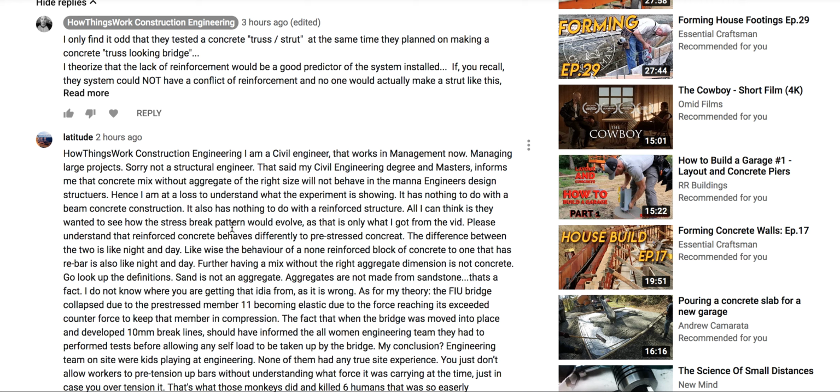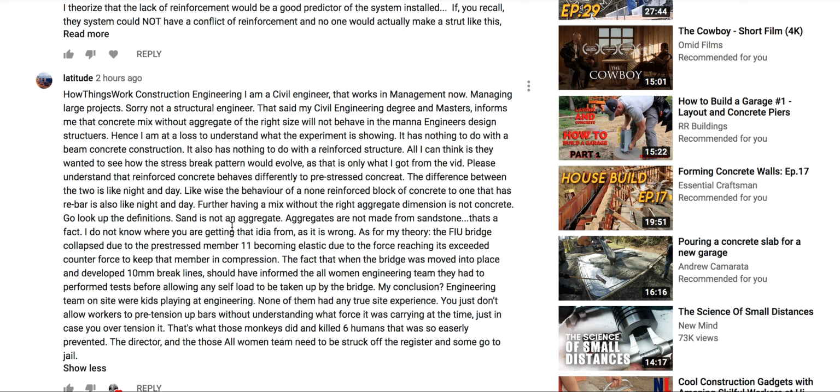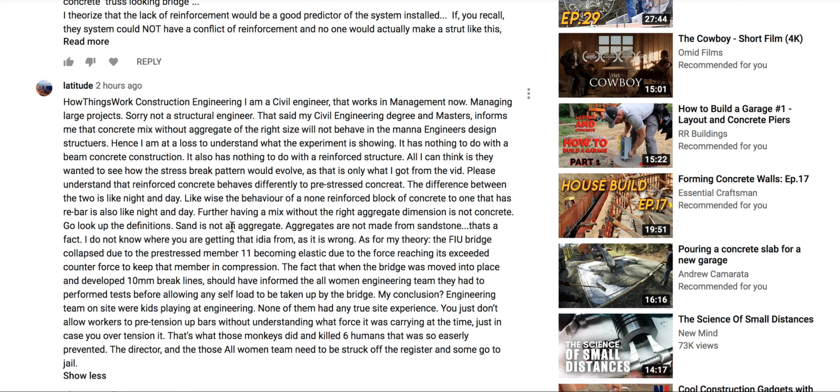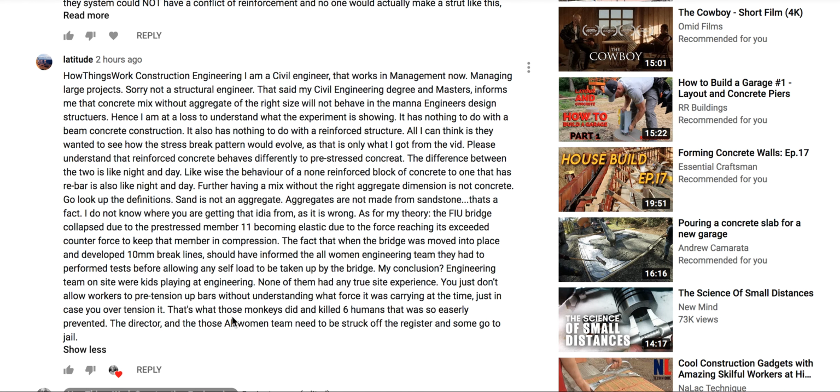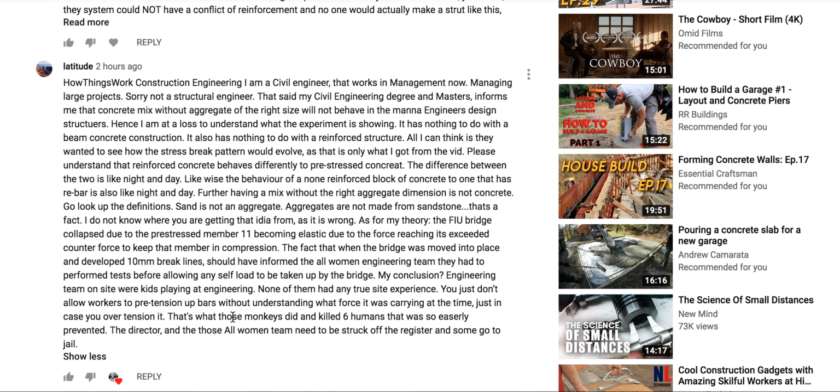I find all cube testing is just defective in nature. No one's rodding 21 times. Any in the field is not being rodded 21 times. I just find that defective to use as any data, and no one's putting it in a lab. So I just find that again to be just defective. Cube testing, I kind of like cube testing. The 2-inch cubes, there's a lot of that going on. But nevertheless, cracks are not mysterious. They always have a reason why they happen. It's not random. So all engineers and all contractors watching this, cracks are never random. There is a reason behind every single crack.